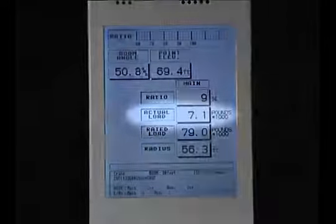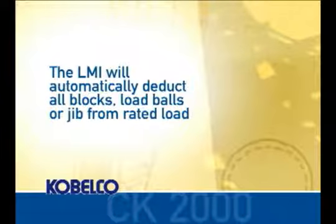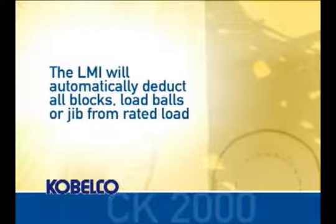The load ratio is indicated here from 0 to 100%. The actual load is the present load on the load block or ball within a 2% error factor. The rated load is the max amount of total weight the crane can pick at its present configuration. As an aid to the operator, the LMI will deduct unused blocks or jib from the rated load. The radius indicates the distance from the center rotation of the crane out to the load block.